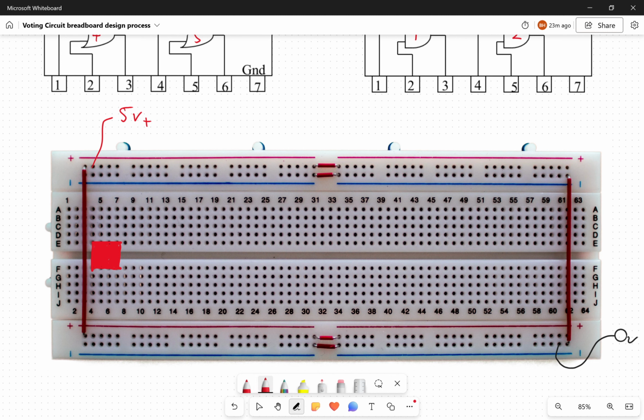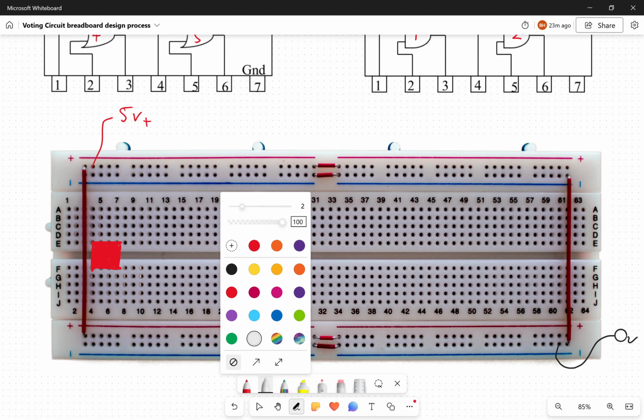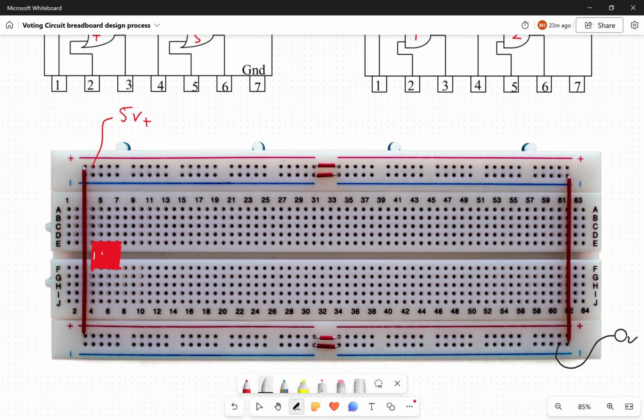Now what you can do is, depending on how much time you've got, you can make it look all fancy and put your 4 little switches on there, which will correspond to the incoming and outgoing signals. And then probably more importantly, we'll have our pull up or pull down resistors, and they are going to go between these switches and ground.